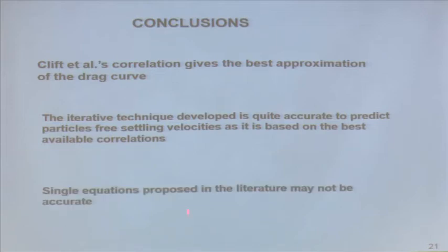And single equations proposed in the literature may not always be accurate. So, be careful when you are using a single equation. Try to identify the core CD and Re correlation that was used for development of that model, and look at the standard drag curve, plot it in Excel, and only then accept that single equation. Otherwise, please do not accept that single equation, even if it is written in any journal. It is my advice.